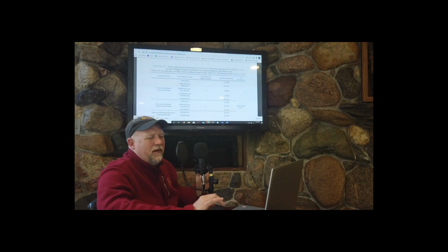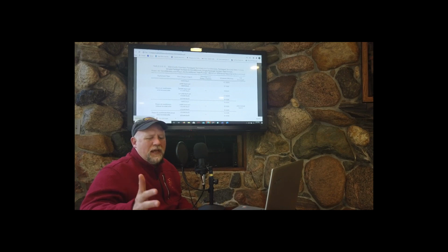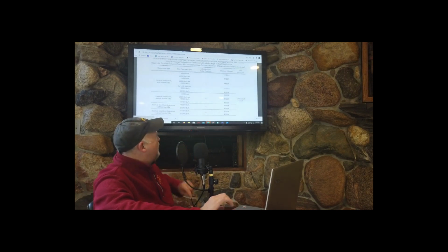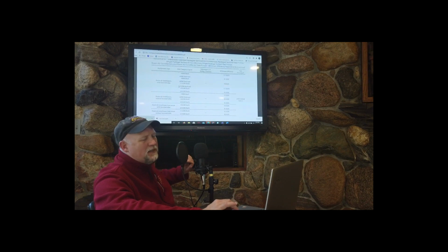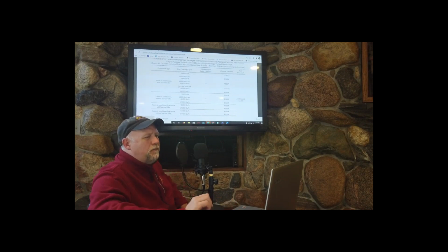We can't use efficiency for air conditioning as a percentage. If we're taking a furnace or a boiler and we're burning a certain quantity of natural gas, the percentage makes sense. But all of these energy efficiency ratios are different forms of kilowatts of electricity consumed per ton of cooling capacity generated. And that's the way I like to think of them.